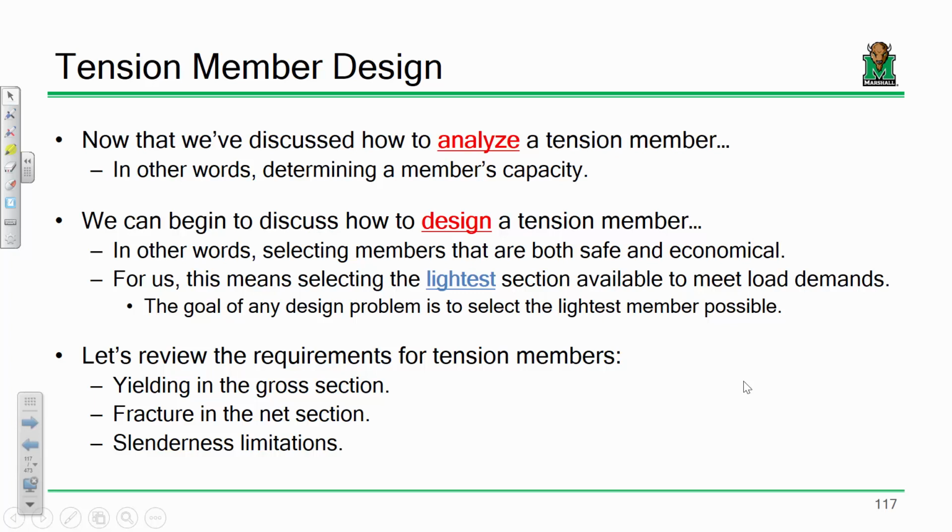But from a real-life perspective, it makes the contractor's job and the steel erection crew's job a whole lot easier, dealing with fewer shapes, right? So in reality land, you might design some members a little uneconomically, with more capacity than they need, because it would facilitate construction.